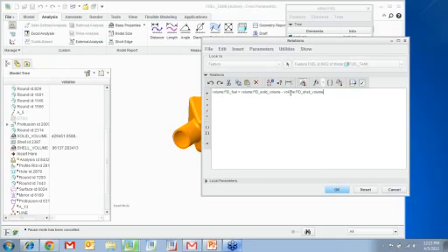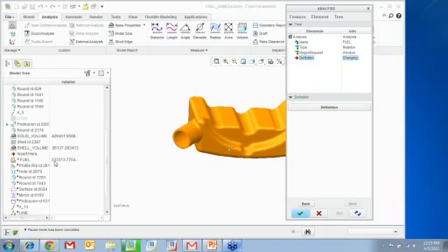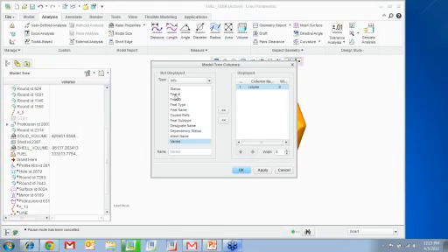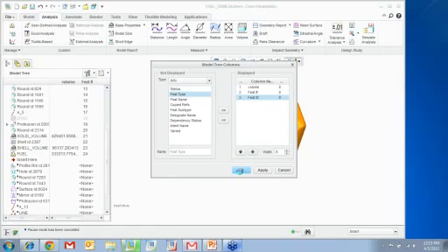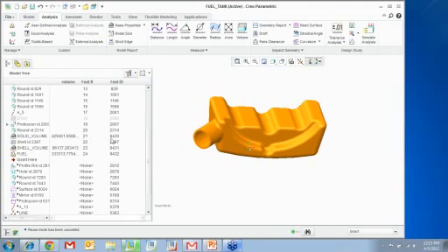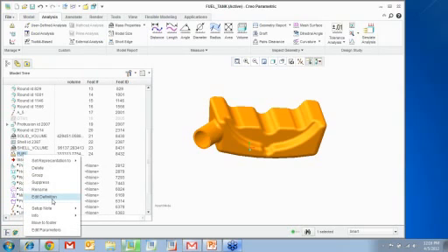Okay, so volume colon FID underscore shell volume was the name of the feature. So you can see that is the volume of the empty space. Now here there is something called feature ID and feature number. So if you go look at feature ID and feature number, you see that the feature number is just a serial number 1, 2, 3, 4, and this is the feature ID. Note that when I write my relation, I'm going to do an edit definition right here.